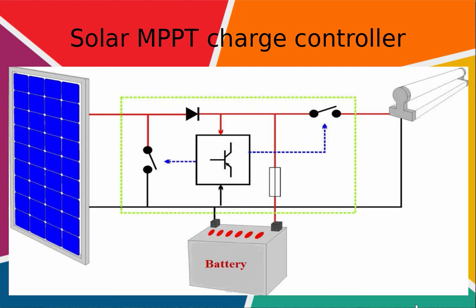Maximum power point tracking is electronic tracking, usually digital. The charge controller looks at the output of the panels and compares it to the battery voltage. It then figures out what is the best power that the panel can put out to charge the battery. It takes this and converts it to the best voltage to get maximum amps into the battery. Remember, it is amps into the battery that counts.